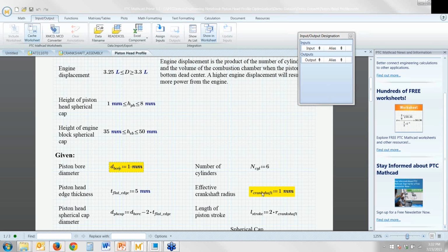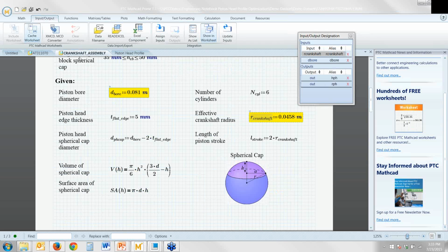The reason for that is basically the moment you insert a worksheet into Creo, Mathcad will make an exact copy of what is on the disk and store it inside of the Creo part or Creo model. In this case, it stores it inside of the crankshaft assembly file. Over here at the top, the path leads to a .asm extension, not a Mathcad extension.